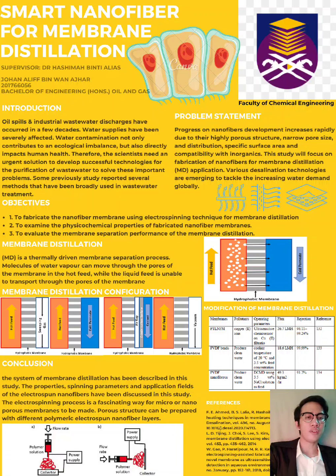The porosity of electrospun nanofiber layers is higher compared with traditional membranes, and the pore distribution is uniform. The highly porous structure increases membrane permeability, while the high surface area makes it easy for membranes to work. Significant progress was found in electrospun membrane manufacturing for water treatment. Nanofibers have a very large specific surface area and a very high surface area to volume ratio.